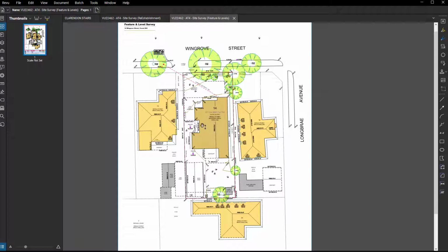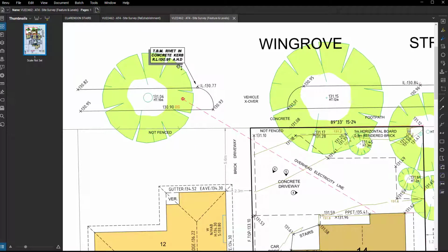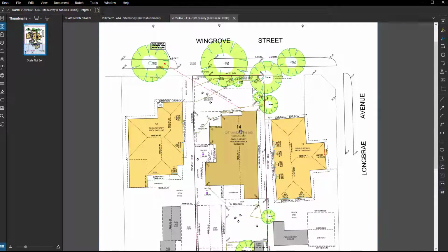So just keep that in mind. When you're working with Surveyor, ask for the points in CSV file and ask with the temporary benchmark, your TBM, to include not just the height reference, but also a coordinate position as well, northing and easting.